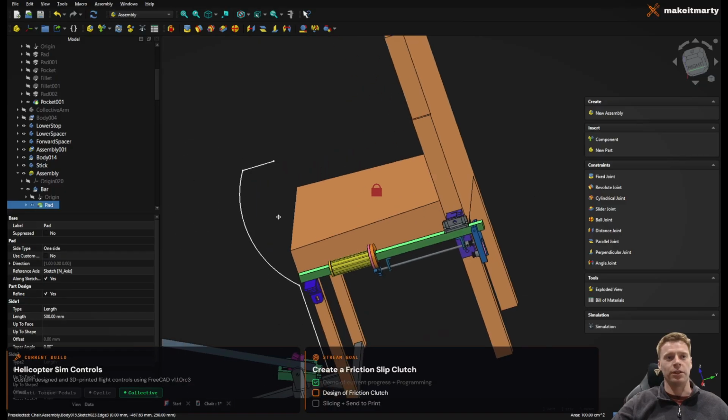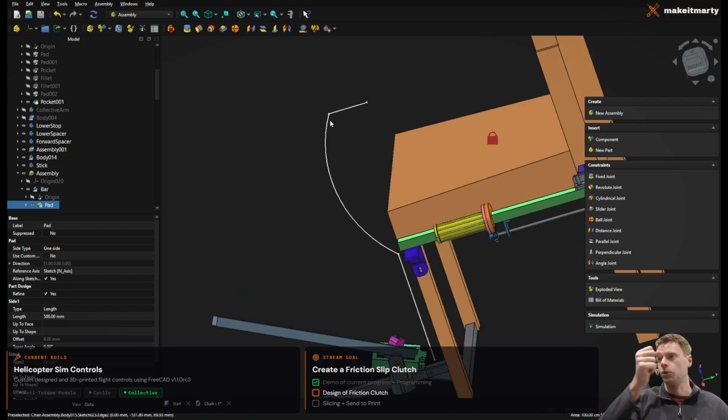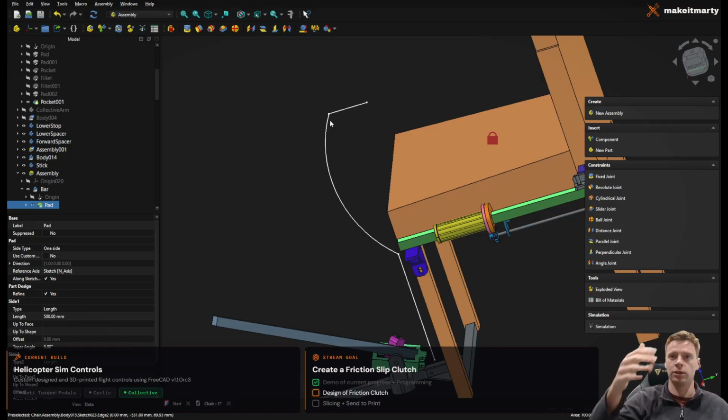If you then, this is the attempt at the collective here. This was just the sketch I used to draw it out. If you were to push the cyclic forward, you have the blades there, and the whole, basically 3 ton, probably on a light one, the whole rotor assembly is then tilted forward, and that's what gives you your forward component. So this is really changing the pitch of the blades, which is giving you your lift, and then push forward for all the blades, then tilt forward.